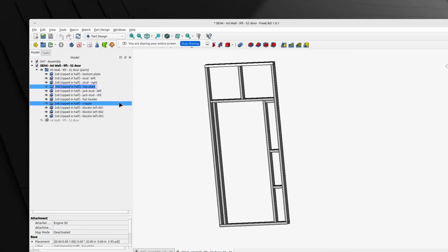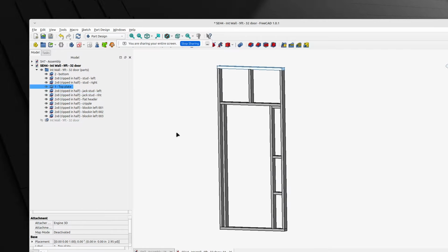Now you can say one, the top plate. Then you continue. The second one is this one, so I right click on it and rename it to bottom plate. You can do that within the part tree, and once you label everything, the entire file could actually contain the whole build sequence. That's one really useful thing I would encourage you to do. Once you download your version, start labeling it.